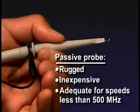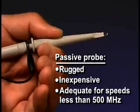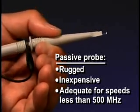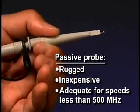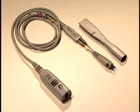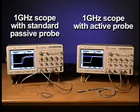High-impedance passive probes offer a rugged and inexpensive solution at measurement speeds under 500 MHz, but at 1 GHz and above, which are becoming more typical, high-impedance passive probes fail to deliver the necessary signal integrity. For 1 GHz and above, active probes are a requirement. Here, we're looking at a 1 nanosecond edge with two leading 1 GHz scopes.